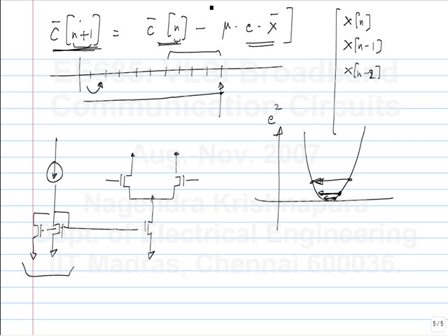Like I said, you can always find a channel that will break the equalizer or the adaptation. It's not very difficult. You just take something of half the bandwidth of what you normally use and it will probably break the equalization. If you have a large value of mu, it will keep chattering around with a large step and that can give you a large error. It's not just the steady state error. A constantly changing value of coefficients is not a desirable thing to have.